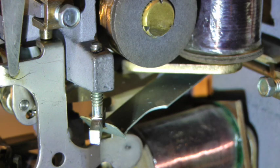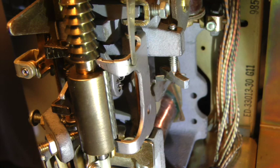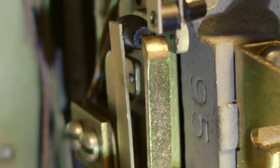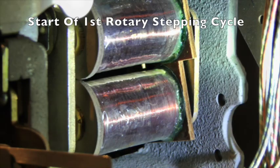When E operates, the vertical armature releases. The vertical pawl disengages from the vertical ratchet. The vertical interrupter springs reclose. E operated also closes the energizing path for the rotary magnet, and so the rotary armature operates.